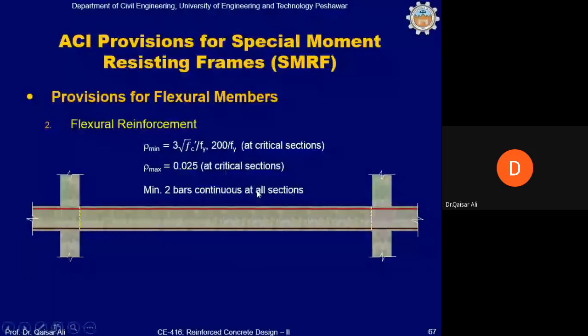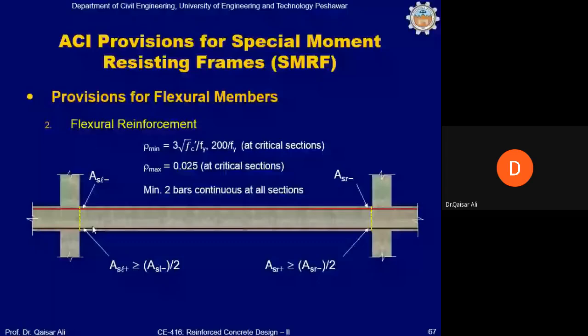Okay. Over and above this, there are provisions for reinforcement, especially at the bottom of the beam, at the ends of the beams. If you remember, we have said quite a few times that additional bending moments are produced in the beam column joints, which means at the ends of the beams and ends of the columns, when a frame structure is subjected to earthquake loading. So these ends of the beams and ends of the columns will be subjected to significant loading due to earthquake, significant bending moments, and significant stresses both at top and bottom of the beams.